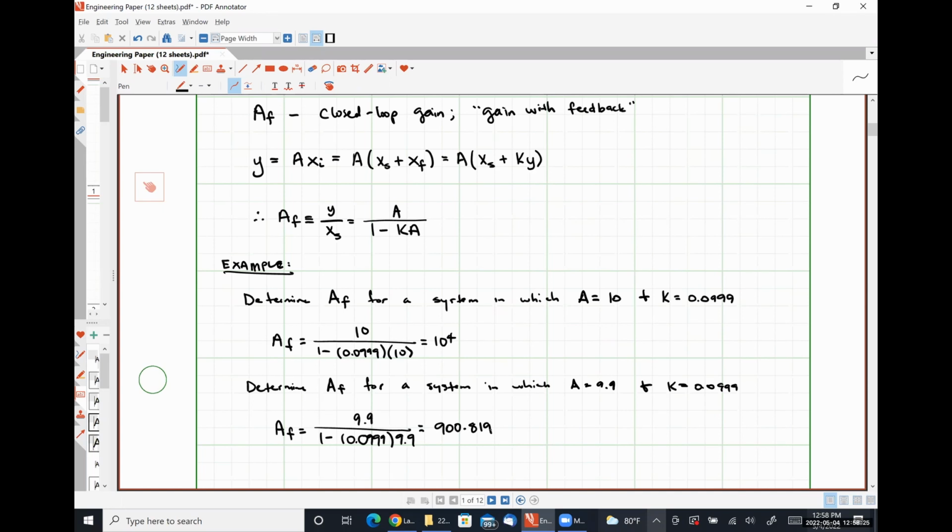It had no input signal whatsoever. If there was even a tiny amount of energy stored in the capacitor, you saw the output voltage swing from VCC minus down to VCC plus and back and forth as that capacitor discharged over your positive feedback network. If you haven't had an astable multivibrator circuit in your 339 lab yet, I think you're supposed to. Maybe you did one in 229, I'm not sure. You should have had a lab on something like this sooner rather than later, but anyway.